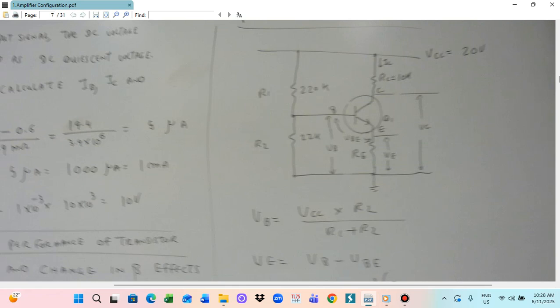So when we are using more than 5 volt supply voltage, we cannot directly supply the voltage to this amplifier, the transistor. So we have to use the potential divider as a resistor. Now I give you these practical circuits that we use, the potential divider, to apply the appropriate voltage to the transistor. So this is what we call the potential divider biasing.